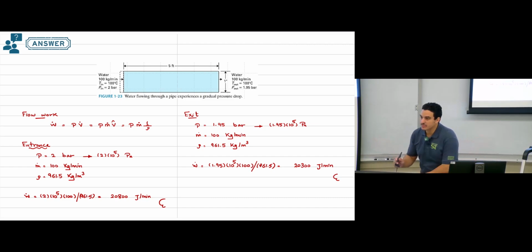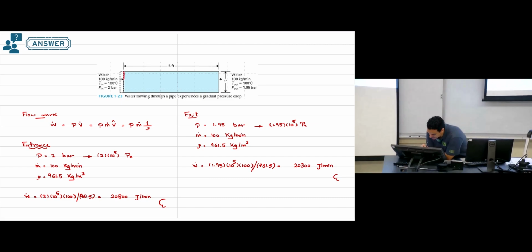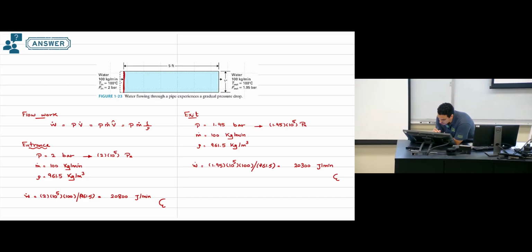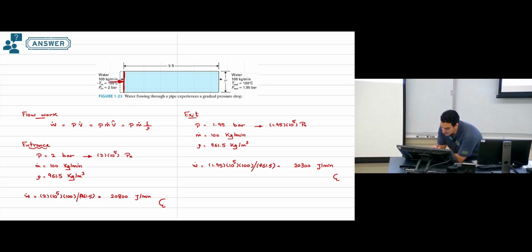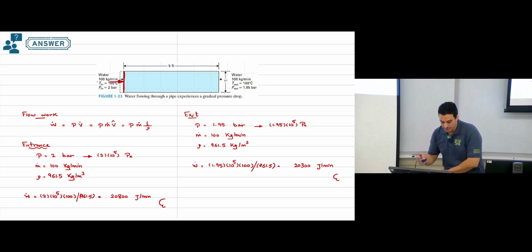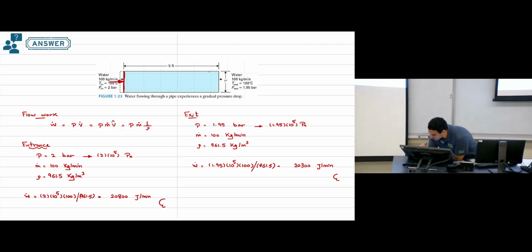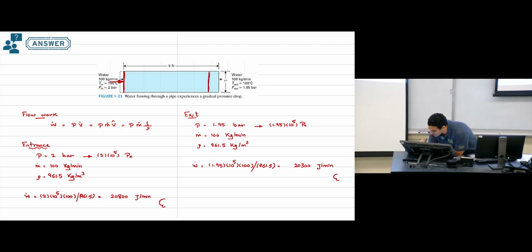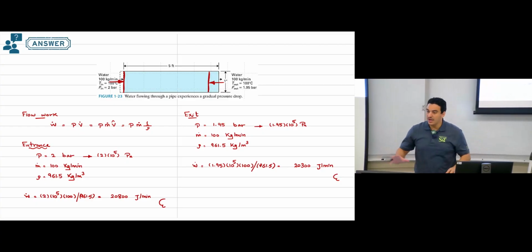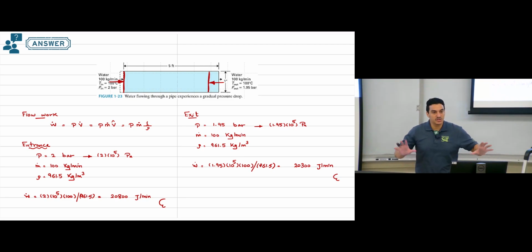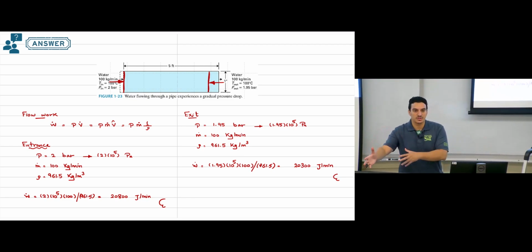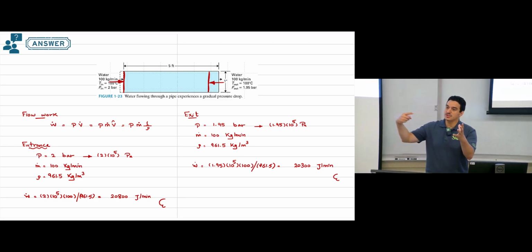And here this doesn't match because let's see, this is the inlet, and as we said, what will be the pressure? The pressure is the normal force, normal to this cross-sectional area. So this will be the direction of pressure we have at the inlet. And for the outlet, if this is the cross-section of the outlet, the pressure direction will be here. So if you have the inlet rate and the outlet rate with the same sign, this means the pressure effect is in the same direction. And this doesn't match because pressure is normal to the area.